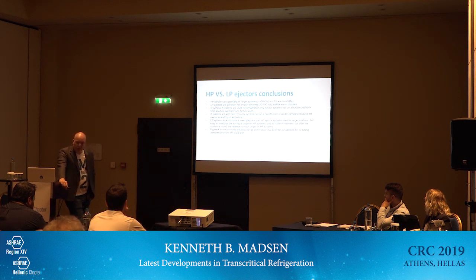We see quite attractive paybacks if we are in warm climates, and even in a cold northern climate, if we can combine it with heat recovery, it makes very, very good sense as well. And then the payback time for the low pressure lift ejector looks even better than the high pressure lift ejector. Just remember that the saving from the high pressure lift ejector is actually twice as big. So if you have a system of a certain size, it's basically creating a bigger revenue for you. So that's also important to keep in mind.